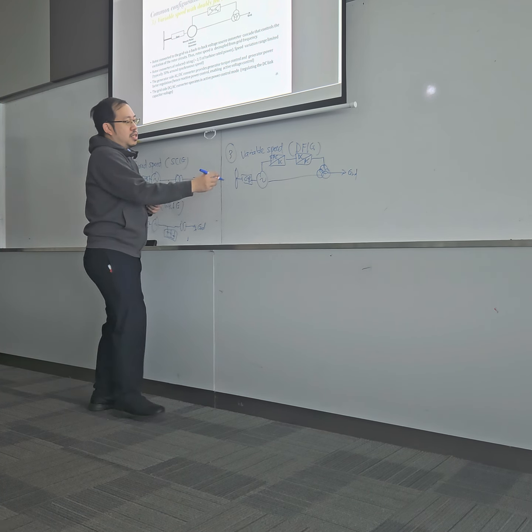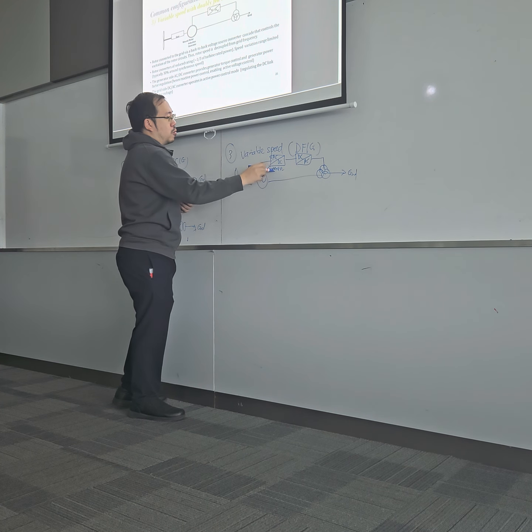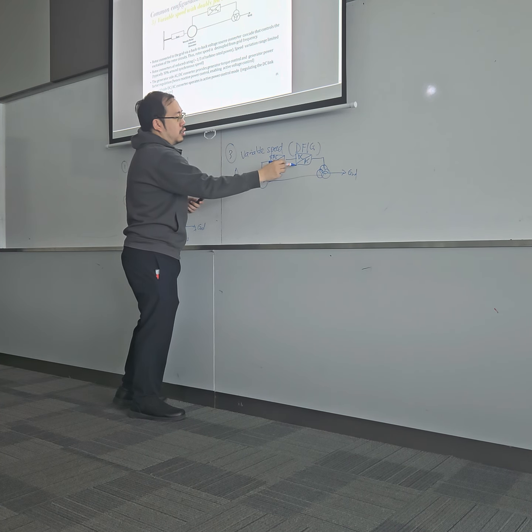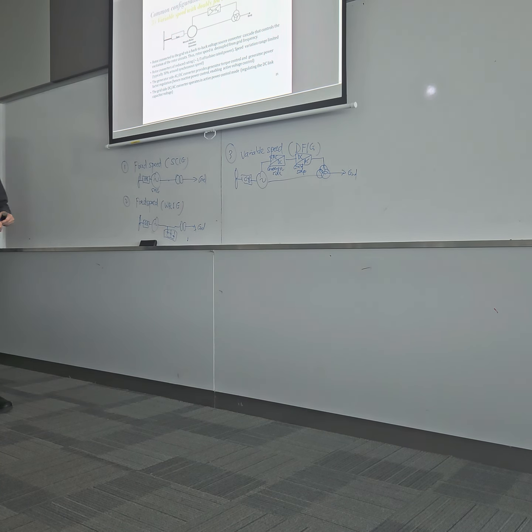Okay, so this is what is called generator side and the grid side. Okay, so when they say generator side AC-DC converter, this one is to provide torque control for your blade. Okay, it can help for your torque control, and the generator side will be for the power factor regulation.